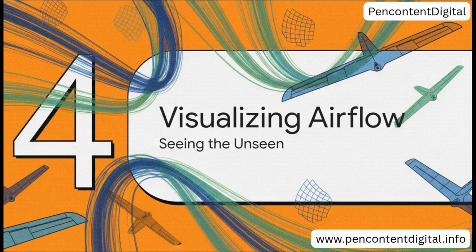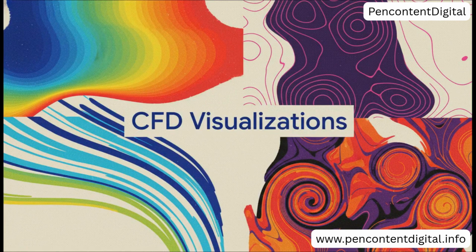This is where we get to see all those solver calculations finally come to life. Once the software has finished crunching those millions of numbers, it generates some truly stunning visualizations. We actually get to see the unseen. We get velocity contour plots that use bright colors to show exactly where the airspeed is high and where it's low around our geometry. We get pressure distribution maps, highlighting the vital pressure differences driving Bernoulli's principle.